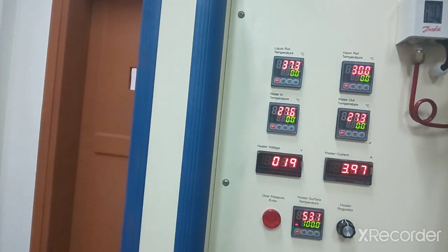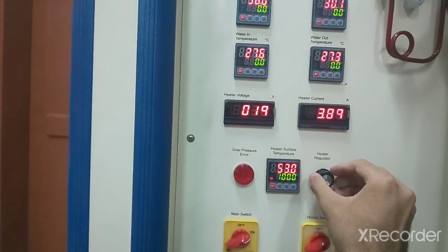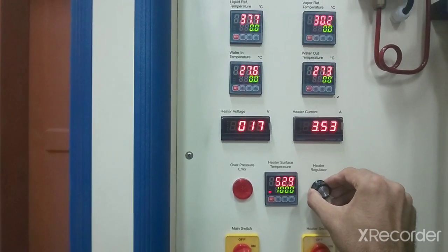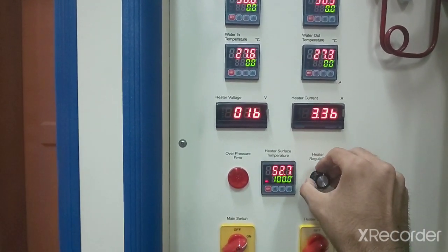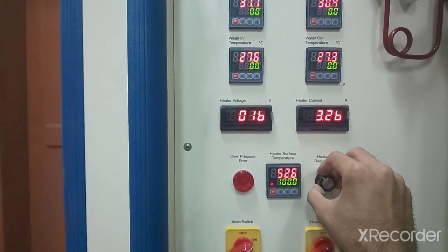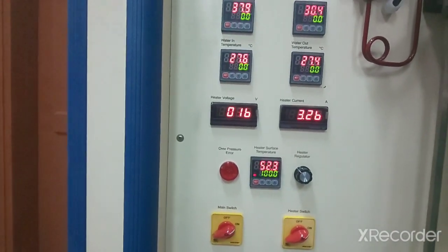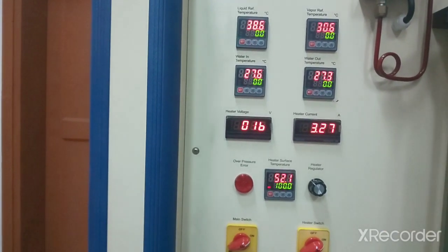Now you can see that the refrigerant temperature is still increasing. And let's decrease it a little bit more so that I can show you the first mode of the boiling. In the first mode of the boiling, you can see the currents of the liquid while there are no bubbles present in the liquid at that time.